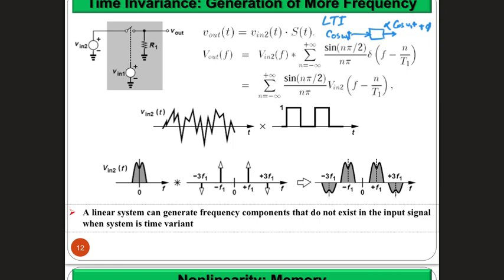Correct? Okay. If this is the case, does this multiplication allow us really to do what I claim that we can do? We see that from your signals and systems background, and again, I'm not asking you to do that mathematical analysis yourself in this course, but just the concepts themselves, and I will explain how this happens quickly here. We agreed already that the output is going to be a simple time domain multiplication of the input signal with something internal to the system, which is this S of t, this square function, right?